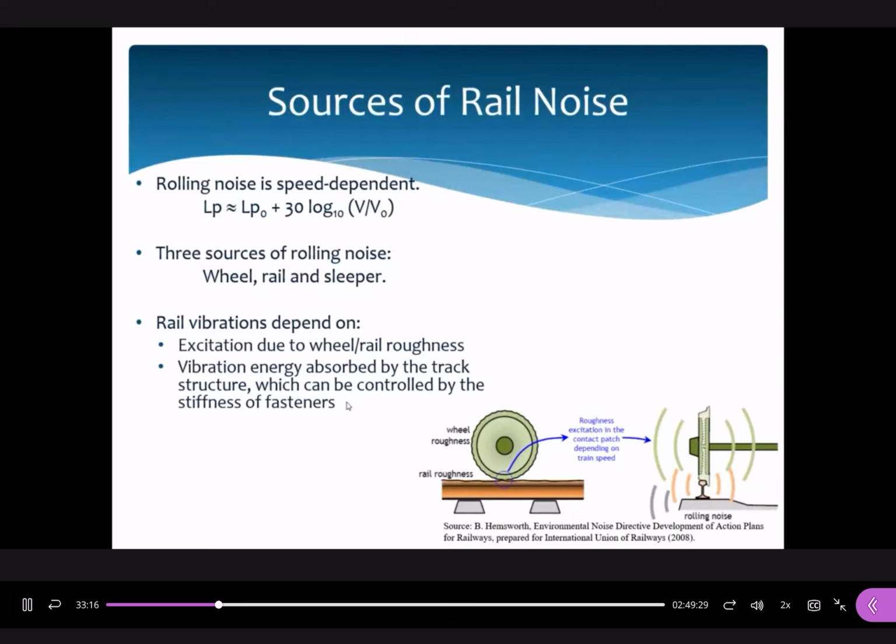And high elasticity, because we just use the ballast materials to support the structure, so in terms of the lateral movements, it has high elasticity. And high noise absorption, but it is just for low speed train vehicles only, not for high speed trains. There are still disadvantages such as the limited lateral resistance in curves, and ballast particles may be disturbed up to cause damage of wheels and trains.